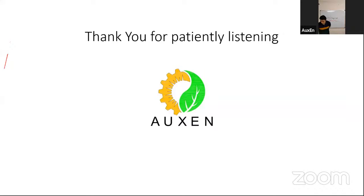Yes, Mr. Vasant is asking whether openings in slab will be included. So see, since we are restricting our discussion to normal suspended slabs, beam column slabs, openings in normal suspended slabs are not a very big issue as such, because you can always have beams around your openings. Openings are a bigger problem in your flat slab systems, but we would be discussing openings as such. What you need to do in detailing near the openings, that we will try to discuss. Okay.